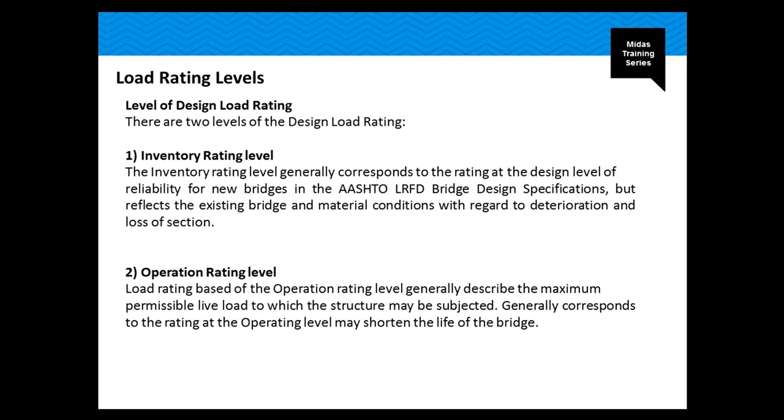For the level of design load ratings, there are two: the inventory rating level and the operating rating level. The inventory rating level generally corresponds to the rating at the design level of reliability for new bridges in the AASHTO LRFD, but it reflects existing bridge and material conditions with regard to deterioration and loss of section. This is the most important part of the rating. It reflects the existing bridge and material conditions.